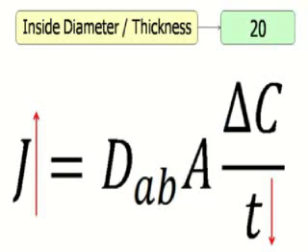So this is the first parameter which will enhance mass transfer. The second parameter: if we take the ratio between the inside diameter of a blood capillary, which is 10 micrometer, over its thickness, which is 0.5 micrometer, this will minimize the thickness of the barrier between the two media. This reduction in thickness would increase the rate of mass transfer to and from the mass exchanger. So Allah God Almighty teaches us here that we need to minimize the thickness of the barrier between the two media in order to increase mass transfer between them.